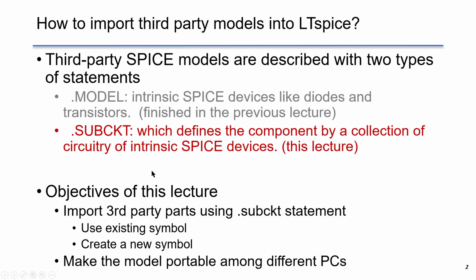The objectives of this lecture are as follows. We want to import the third-party models using the .subckt statement. We will learn how to use existing symbols, and another method is to create a new symbol. In addition, we would like to make the model portable among different PCs.